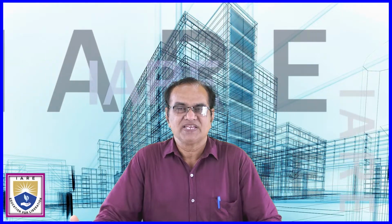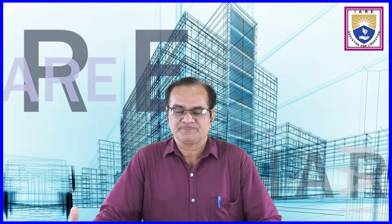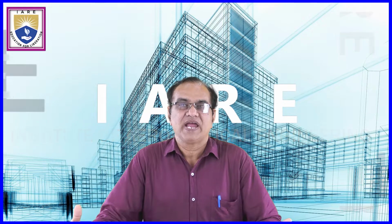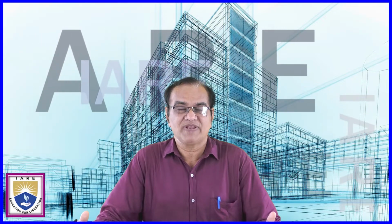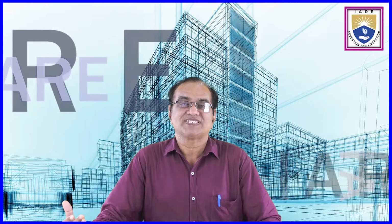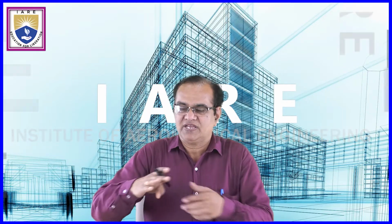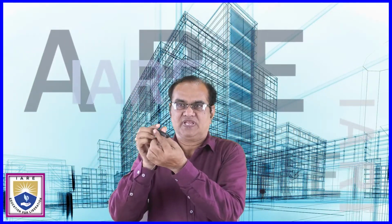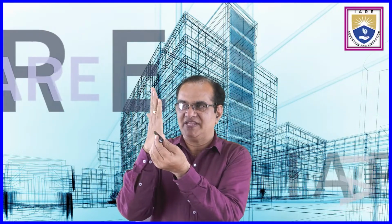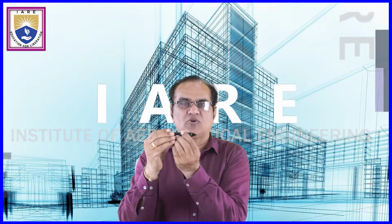Second one is the vertical stabilizer. This vertical stabilizer provides yawing moment and lateral and directional stability. There is a rudder. This rudder is used to give the motion about the z axis, or the yaw axis. In this, the nose will go left or right, like this. This is yaw left, yaw right, and this is happening by the motion of the rudder. If you move the rudder left or right, your nose will go left and right.